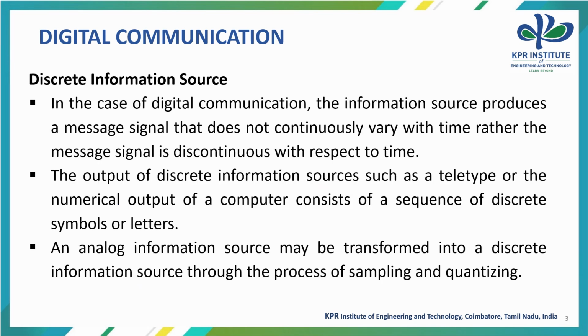Let us consider the discrete information source. In case of digital communication, the information source produces a message signal that does not vary continuously with time. Rather, the message signal is discontinuous with respect to time. The outputs of discrete information sources, such as teletype or the numerical output of any computer, consist of a sequence of discrete symbols or letters. An analog information source may be transformed into a discrete information source through the processes of sampling and quantization.